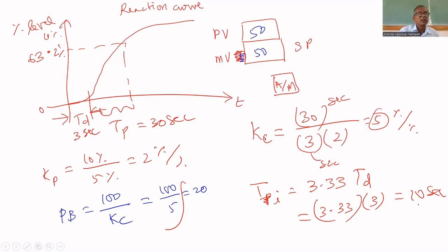Note down this value. If for any disturbance the controller controls the process, then it is called regulatory response. Now you are changing the set point after changing to closed loop. Now it is in closed loop. Instead of 50, you are changing the set point to, let us assume, 55.